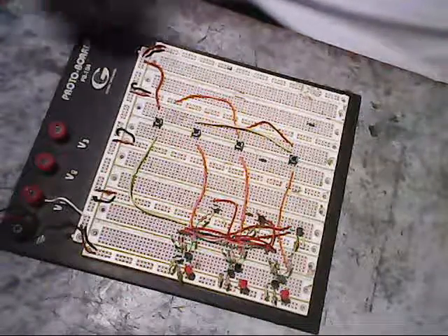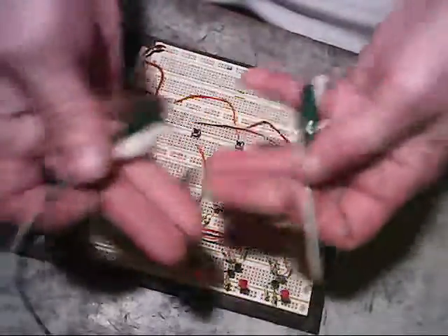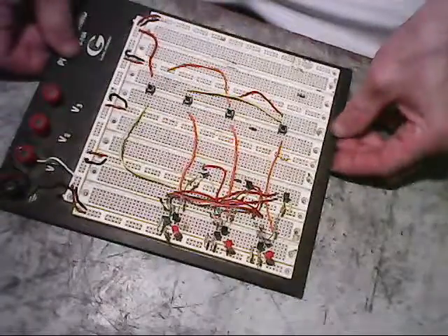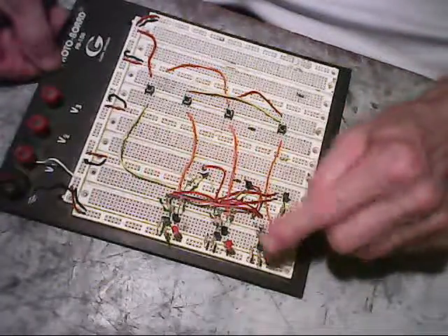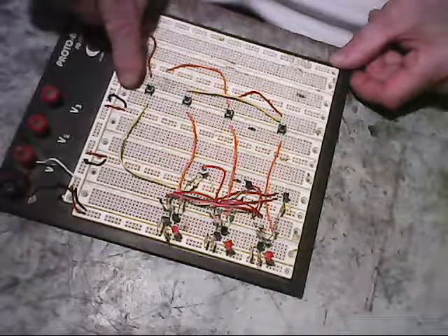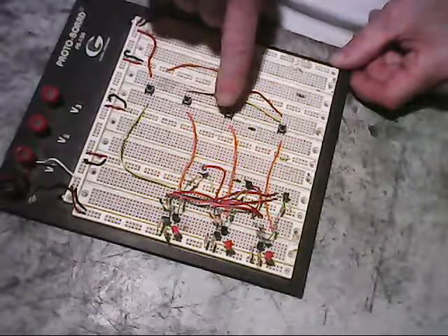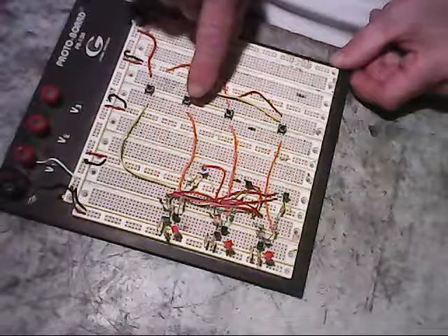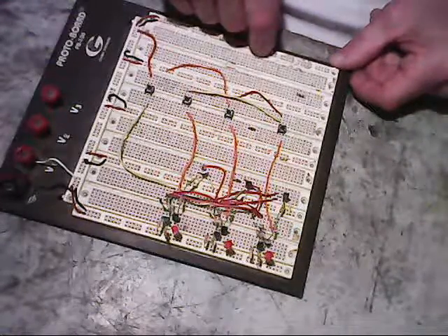I can remove the test wires I was using. Don't need those now because I've got buttons in here now. And the circuit's completed. We have our first cell, the second one, and the third one. This button here would be the all clear. That's connected to the negative side of the battery. These three switches are connected to the positive side of the battery. That's our positive input. And let's give it a try.